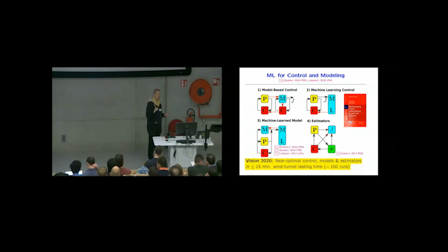you can increase your sensor signals. You can go from 1 to 20, probably 100 sensor signals, and your learning speed will be approximately the same. Because at some point machine learning listens to the sensor, there's some redundancy, this works. But if the actuation is not strongly correlated, if you do different actuations at different points, if you have to use different frequencies and so on, then the learning time increases. And so my rough estimate is the learning time is proportional to the logarithm of the number of actuators, assuming that the actuators do something different, which is a small increase.